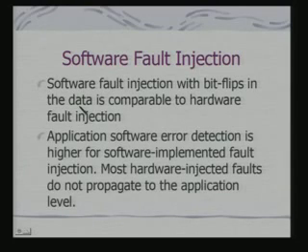Typically, stuck-at faults would give you what? Bit flips. So, I can flip data in the memory and see whether the system is working correctly or not, what the behavior is, and whether it can be taken care of or not. And at an application level, the software error detection is higher.